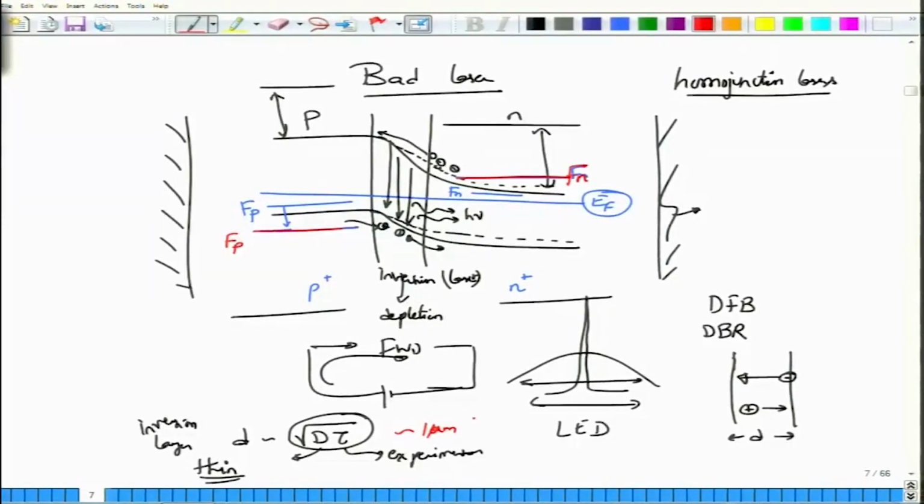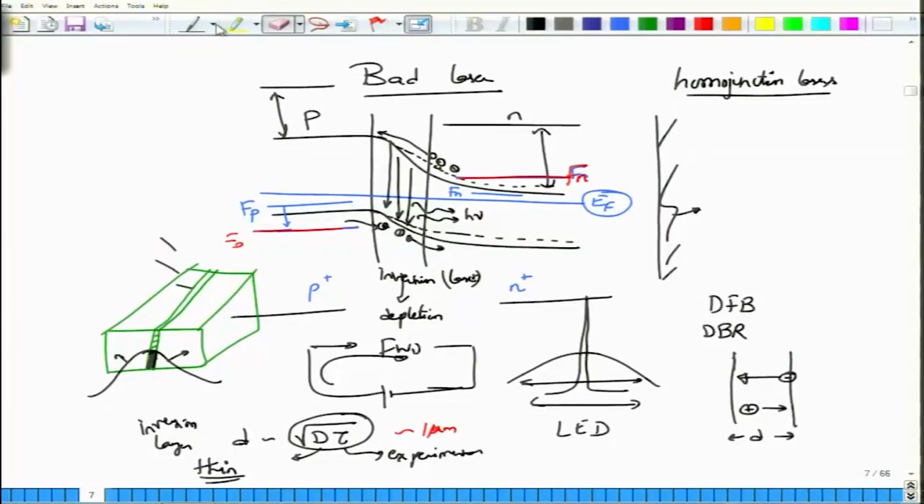1 micrometer is usual. And if you now look at the optical signal here, the optical signal or the optical mode would be coming in this direction. So, if you actually look at a proper PN junction, this is how the junction would look like. So, this is the thin region over which you have created the inversion, and the optical signal would actually come out of this facet in this form, or actually move into this facet in this form. It is created at one face and at the other face it would actually come out in this way. Only this region is seeing the gain and these tails are actually seeing a lot of absorption. So, with the effect that at the output of the semiconductor, what you would see is a very highly developed gain region, which is quite small as well, but almost no energy or no optical mode at the edges because of this absorption at the band edges.